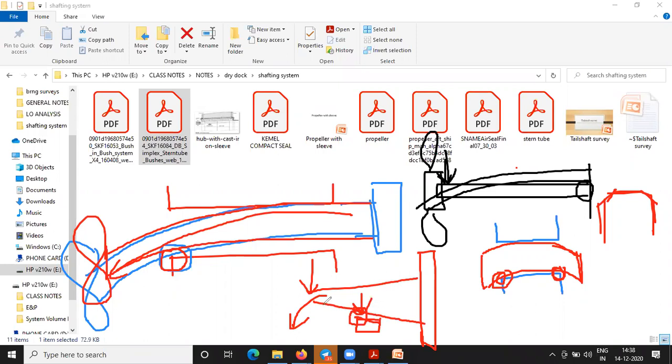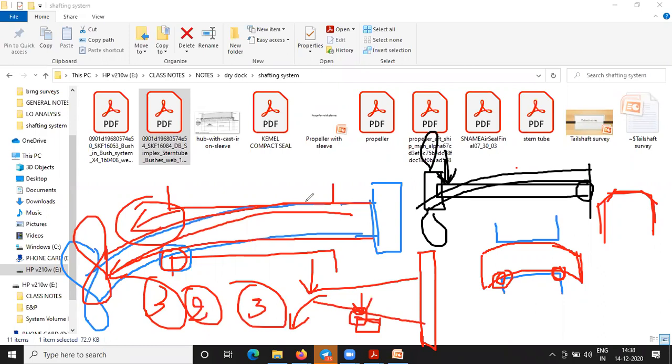Yes, sir. So you understood, Indrajit Singh? Yes, sir. And one more thing, see, three reasons. One is we are reducing the weight of the shaft at the tail end. Second thing, easy fitting and removal. Third thing, the edge loading is reduced. So answer all the 3 points so that the complete answer for the tapering includes all these 3 advantages. That's why 1:100 taper, right, sir?